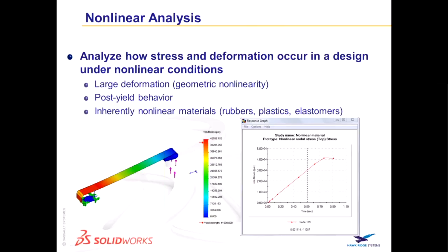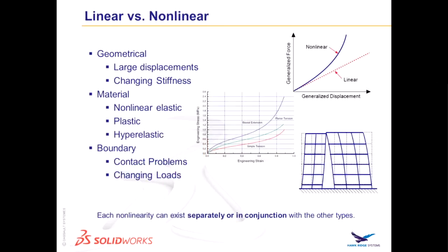And as you're able to see there in the screenshot below, that means, again, we can handle things that deform a lot, and that we'll also be able to see response plots of how much they are deforming as we apply the loads. In addition to the geometrical and the material nonlinearity, the last one is that in the nonlinear static analysis, we're also able to change the loading conditions over the course of the analysis that we run.